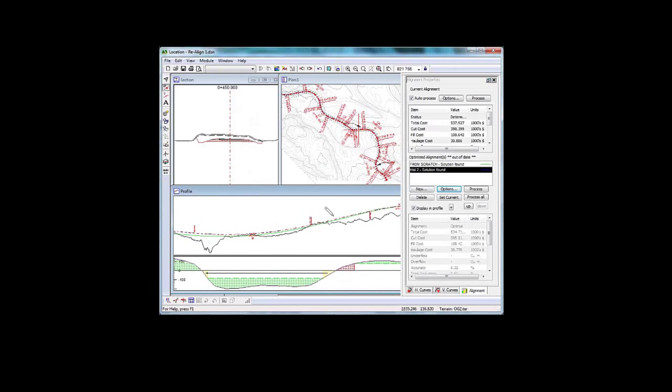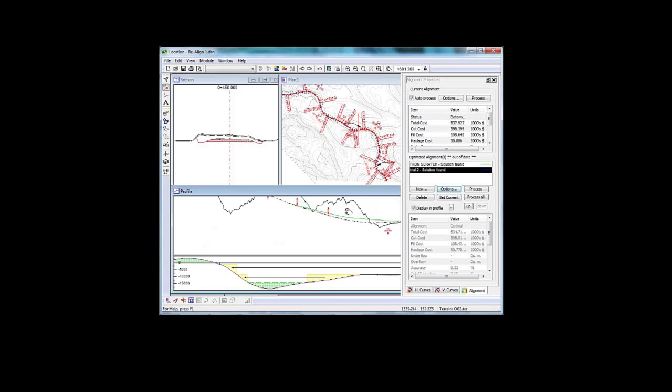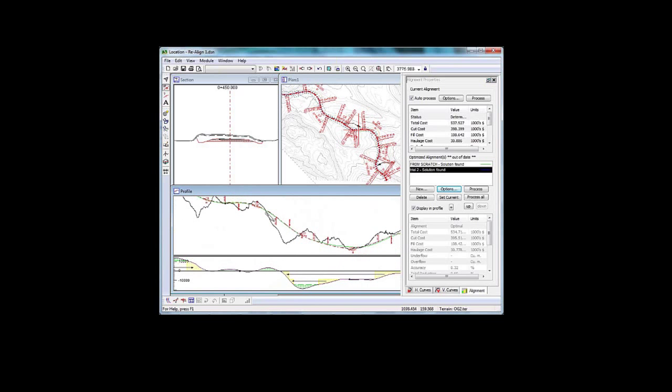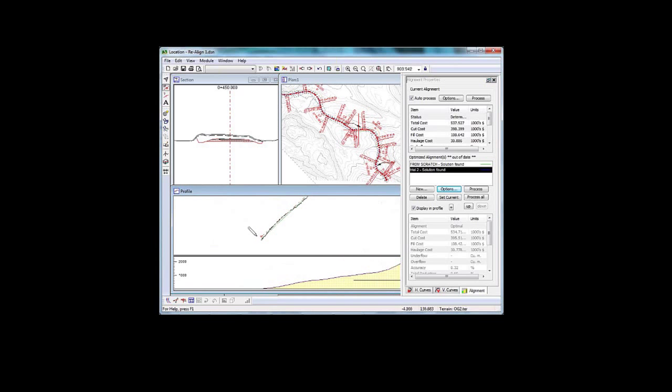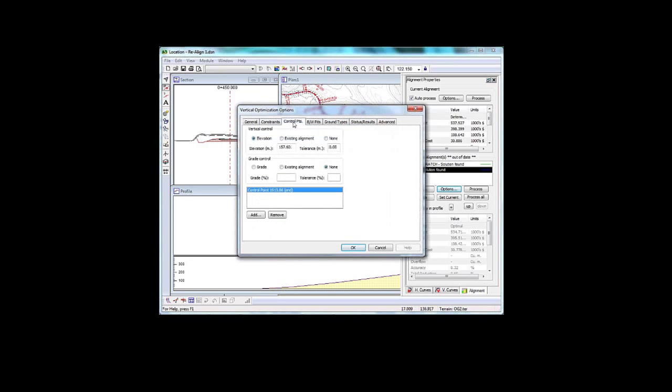Same at the beginning. If you've got an existing alignment, if you've gone to the trouble of creating an alignment, so I want this one to be at elevation 136.3, is that right? Sure, 136.3. So we'll add one at the beginning. And let's make that 136.3.